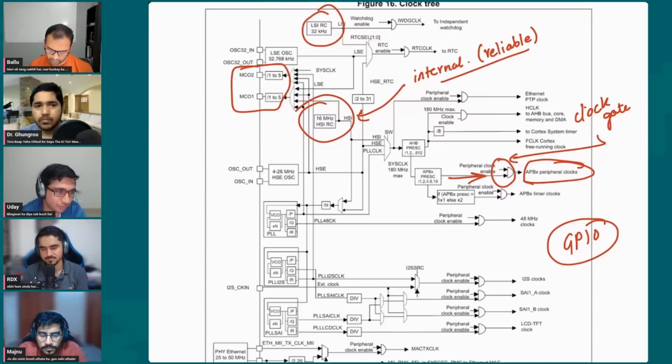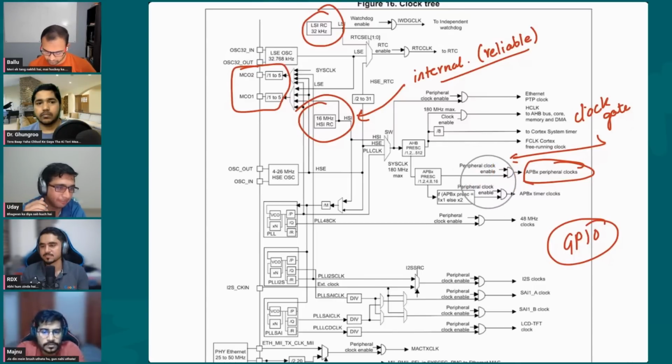This is very crucial to know, because it is wrong to assume that as soon as you power on the device, your peripheral is getting clocked. This helps save static power consumption, and that's why designers clock gate the IPs. Which makes sense. So now we know how to flash our device, and how to enable any peripheral. And the third most important thing to get the blinky LED working is to know how to toggle a GPIO.